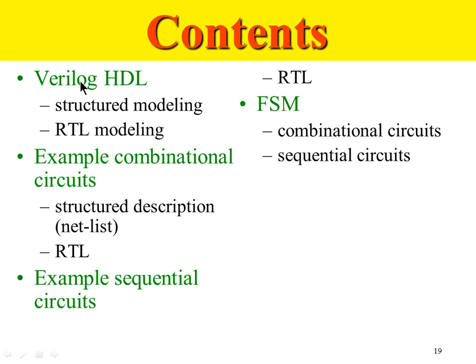It's a language based on description of the circuit, and that is one method to design digital circuits in Verilog. The second method is structural modeling, like schematic design. In schematic design, we took a few gates and connected the inputs and outputs of each gate to the appropriate connections. We can use the language to create that structure in Verilog. That's called structural modeling. That is still done when there are very critical, mission critical designs. We might have to do a little bit of structural modeling for that purpose, but very rarely do you use structural modeling. But it is still there as a part of the language.